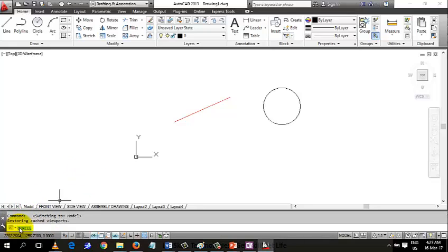Then if it is graphic, you can pick buttons. AutoCAD also works with buttons. Instead of typing line, I can come here and pick line. The same thing is going to happen. Look at it. If I click line there, you see line specify first point. Now let me escape and clear the command window by pressing the escape button. If I type line and press enter, the same thing also comes out. Line specify first point. So either you type line here by character or you pick a graphic button, the same thing happens. So that is AutoCAD for you.